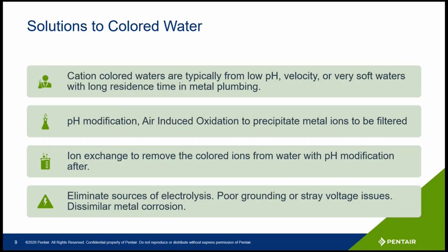Even super fine sands or silicates may come out of wells, or just overwhelming iron deposits in particulate from wells, where it's in a broad spectrum of particle size and you're getting colloidal iron through that's staining everything and just coating everything with it. And it's really a particulate issue. You can't remove that with a water softener or an iron removal system. It's already particulate and it's blowing through your existing equipment.